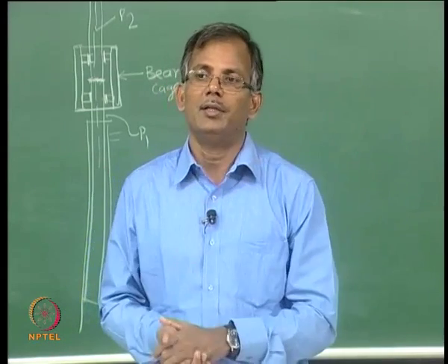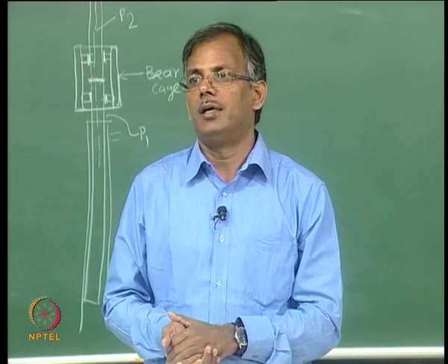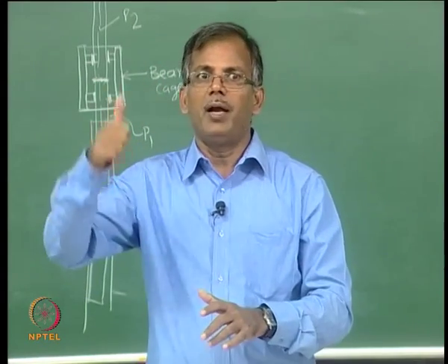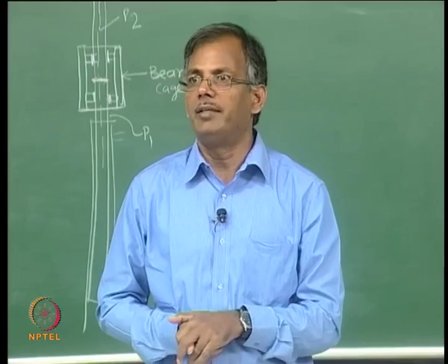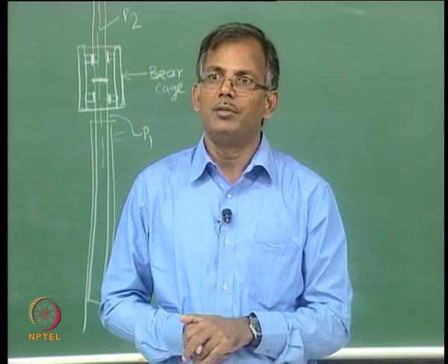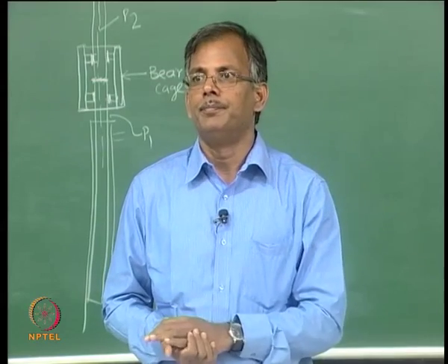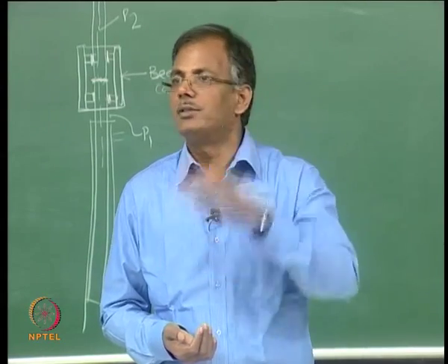We call it dead weight load testing. Now, imagine if I have to get a 1000 ton weight offshore to do a pile test, it is going to be a big challenge, taking the material there and bringing it back, forget alone the reaction frame and all that.